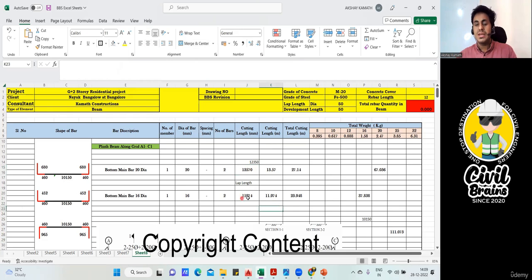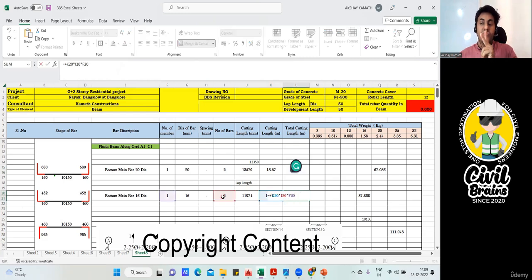Finish. Now this is in mm. I'll convert this into meters, so this divided by 1000 will give me 11.974. Now coming to the total cutting length, 11.974 into number of bars, which is 2. Number of member is 1. So my total cutting length will be 23.948.